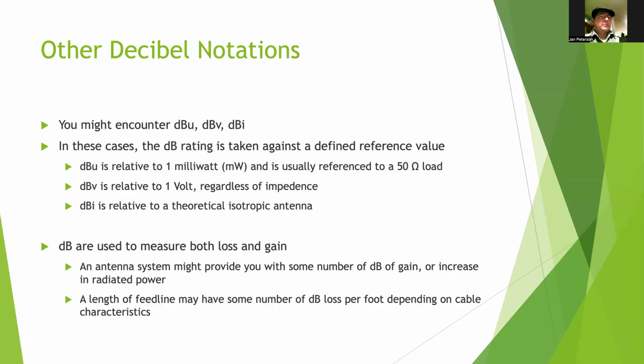What does isotropic mean, in dBi? So an isotropic antenna is a theoretical antenna that radiates power in all directions equally. Any normal antenna is going to have some kind of pattern that it radiates power in. Like on Sherwood's rubber duck on his radio, it's going to come out more to the sides than it does straight up.